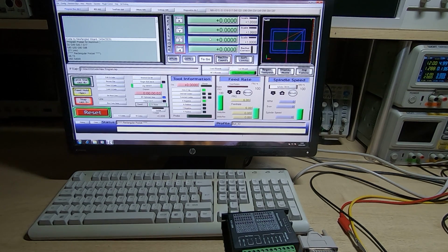So we'll run through. That's fine if you're using just one tool, that's all you need to do. The problem comes, of course, if you have to change the tool partway through a program, because you either have to get the tool exactly the right length or you have to re-zero it. And this is, I think, where a lot of the confusion comes in with Mach3, and it causes a lot of people to get frustrated with it and give up, and I'm hoping to try and head that off in this video to a certain extent. And it's really understanding how Mach3 works.